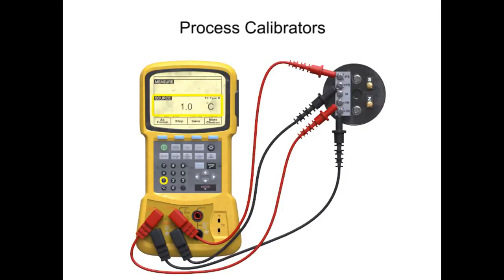At the high end of the temperature range of 100 degrees Celsius, the expected output of the transmitter is 20 milliamps. Calibration is performed by using the zero and span adjustments to tune the appropriate current value for the simulated temperature.